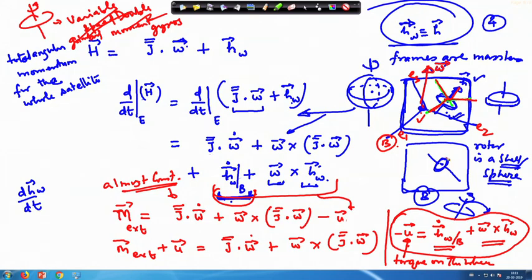So, what I was stating is that in addition, if your wheel is also speeding on its own axis, that means you have 3 degrees of freedom. One is coming from psi, another from theta, and another from phi. Already it is rotating at the rate phi dot, but phi dot you can speed up. So, that constitutes another degree of freedom, and this can be used to produce the 3 axis control torque. While here in this case with psi and theta only varying, you can produce only 2 axis control torque.